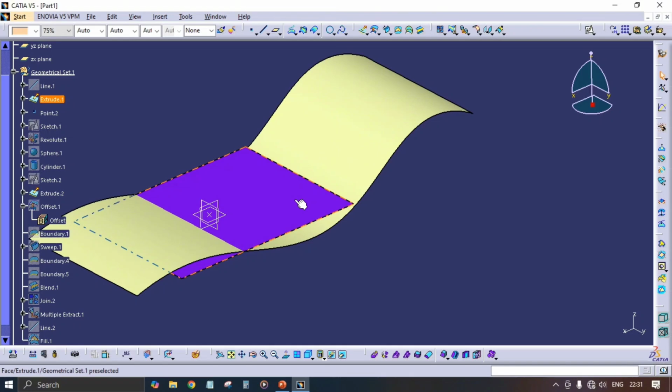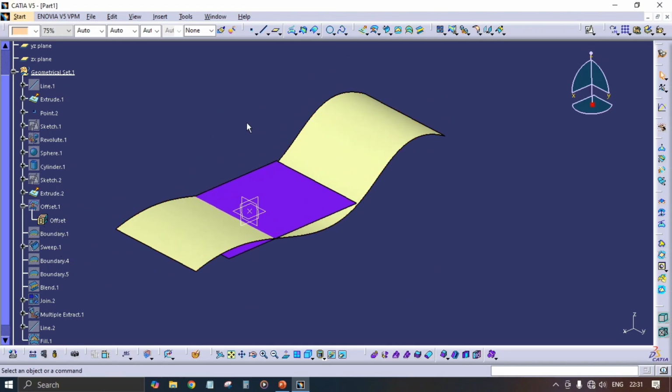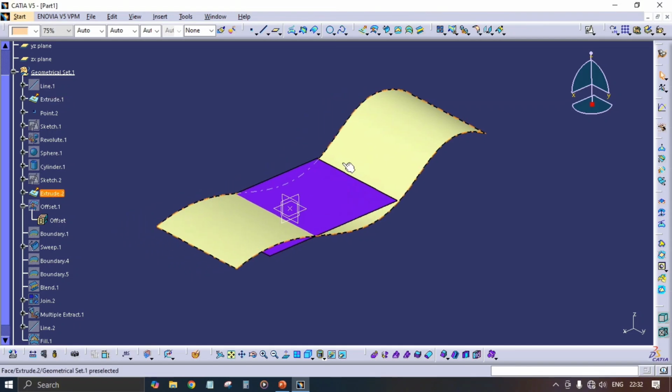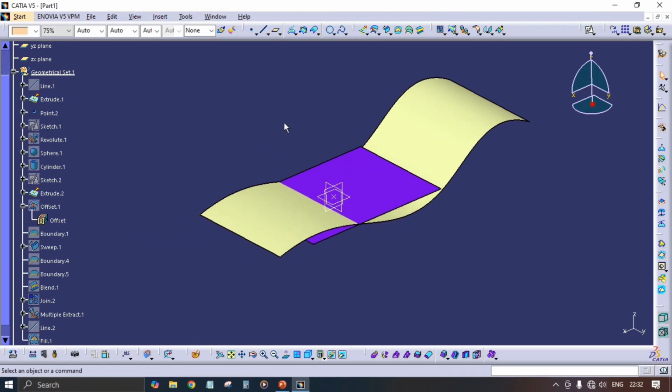In some cases, for checking purposes, when we are using a closed body, we have to create a class B surface and a class C surface, and then trim class A with B and class A with C. In those cases a lot of errors will form. In order to check where the problems are forming, we use the intersection tool very much.